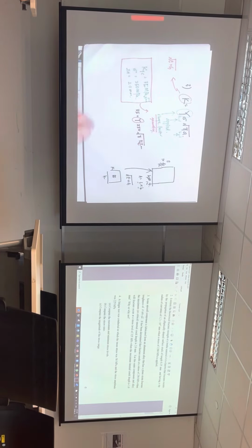For the next part, for the same component and alloy, whenever you have the same component, alloy, even the same shape, they will always have the same Y. So for the next part, the Y is the same, and now you found the Y already. They're asking you, will fracture occur at a stress level of 350, where the maximum internal crack is this one.